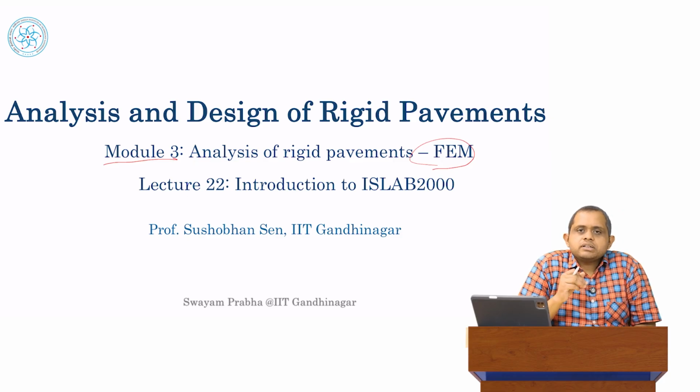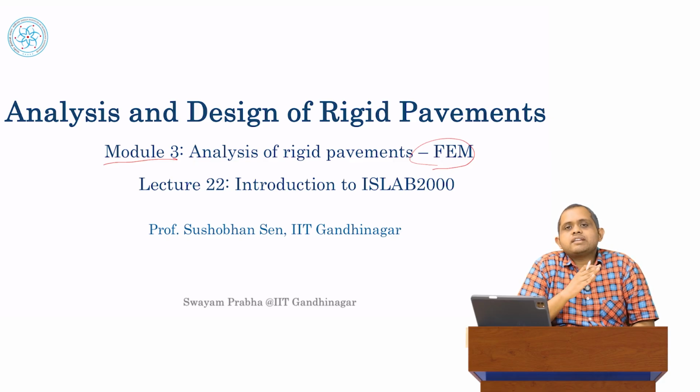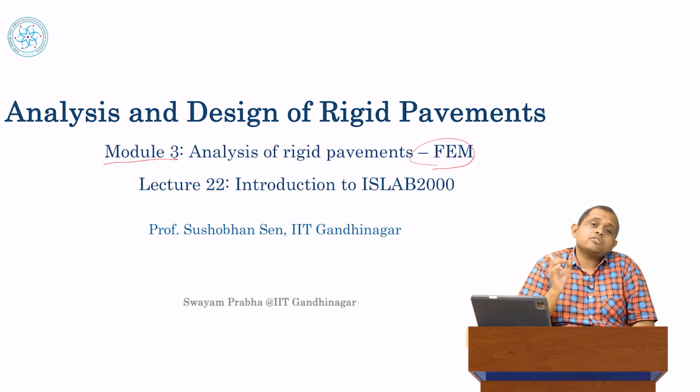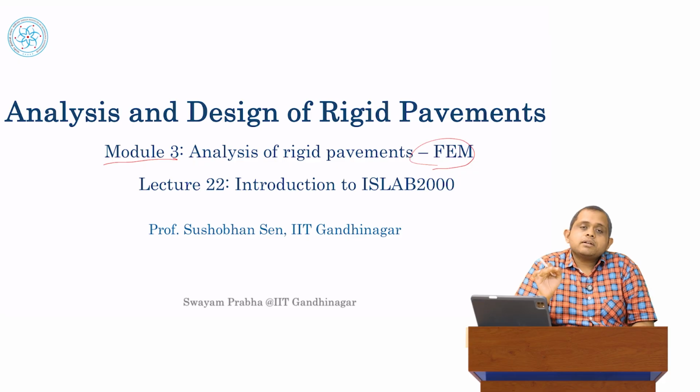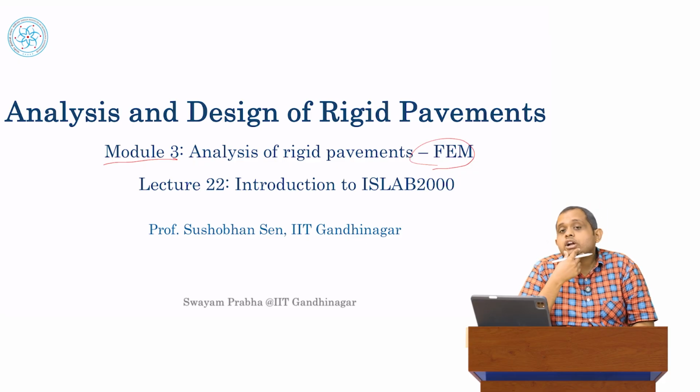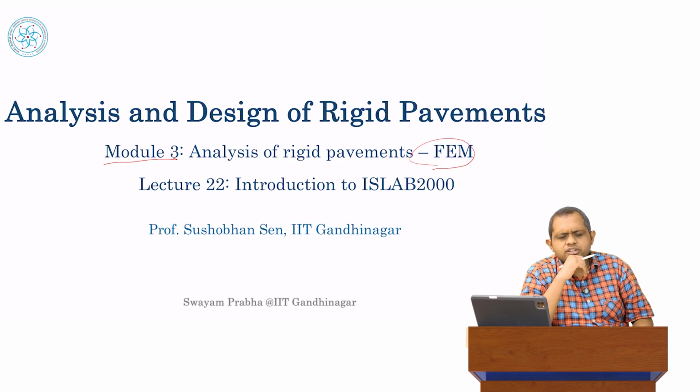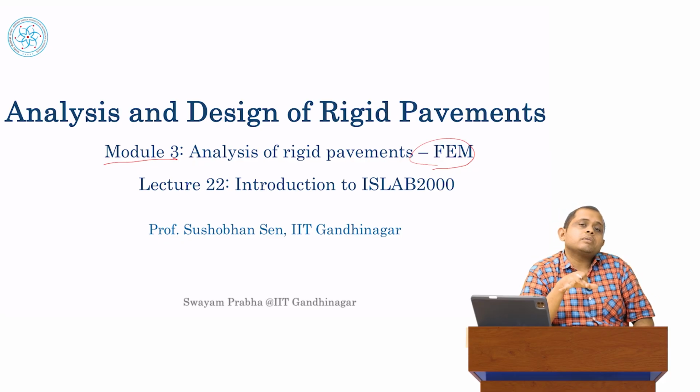Now, the reason why the finite element method has been used is because it takes a radical departure from these analytical methods. Again, the analytical methods start with certain assumptions. The assumptions may be wrong, but under the assumptions, they derive certain closed form solutions, certain formulas, and they allow you to calculate the response of the pavements without any error besides whatever error is coming from the assumptions. The finite element method goes in the opposite direction. It does not make the same assumptions. So the large slab assumption, the circular loading assumption, the assumption of tensionless or tension springs, etc. None of those assumptions are made in the finite element method. So we eliminate these unreasonable assumptions.